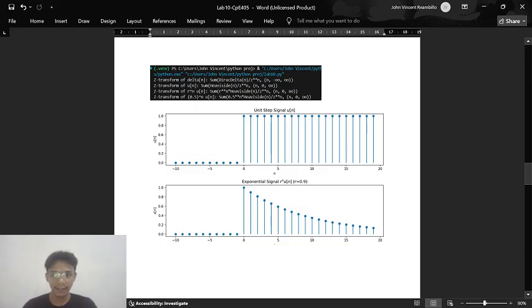We then explored the Z-transform for a practical example using 0.5 raised to n u[n] and calculated its inverse Z-transform numerically. By plotting the inverse Z-transform, we confirmed that the original time domain sequence is recovered, which demonstrates the consistency and the usefulness of the Z-transform in analyzing discrete time signals.